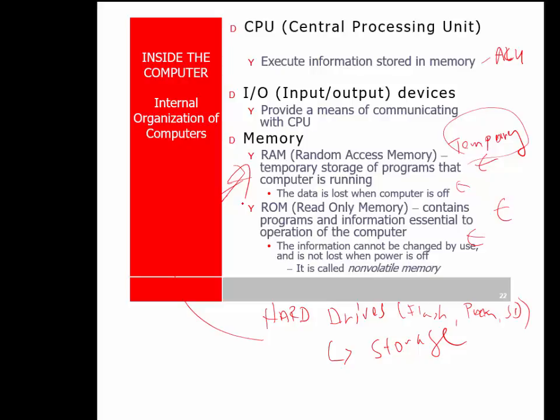For this slide, the takeaway is really that RAM is temporary. You lose power, it's gone. ROM is read-only. You can't write to it, as a general rule. That is also not true, so I'm spending a lot of time on this slide. ROM used to be program it once and you throw it away if you want to erase it. You could not erase ROM back in the old days. That is not true today. Most systems have some type of upgrade or firmware update where we can rewrite the ROM.